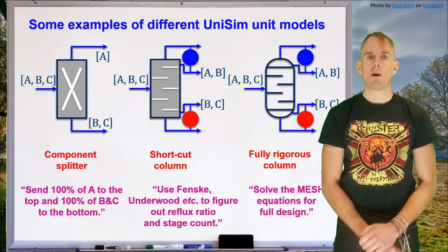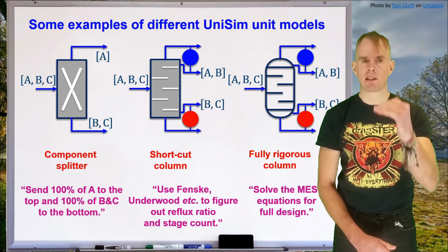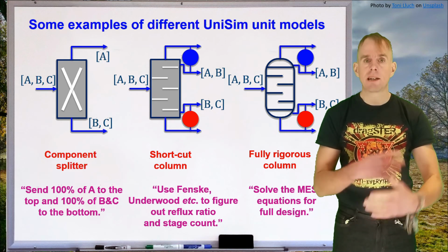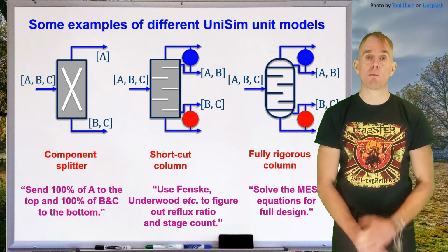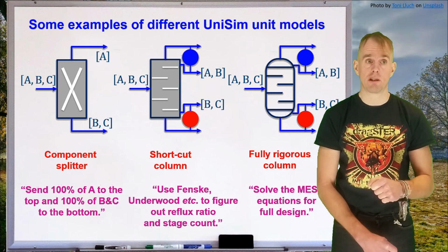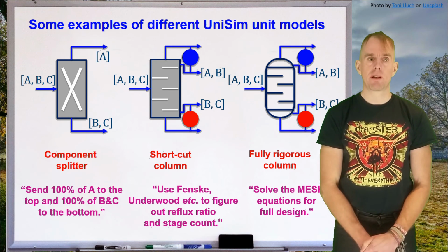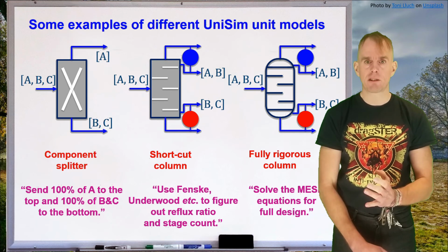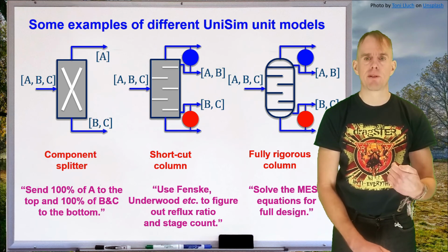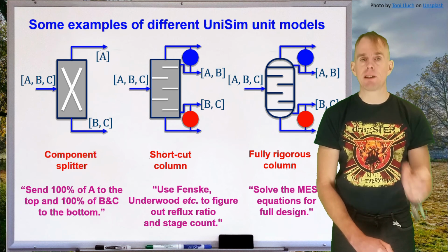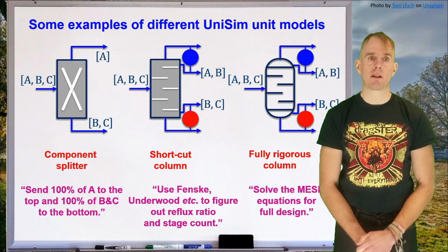Within this tool, all the complete heat and mass balances are being solved theoretical stage to theoretical stage, and you're actually getting a prediction of what a distillation column would physically do under those conditions. So again, 3 different tools that can perform very, very similar tasks, but in very, very different ways, requiring different levels of information to start and giving different levels of information when they complete and successfully run.